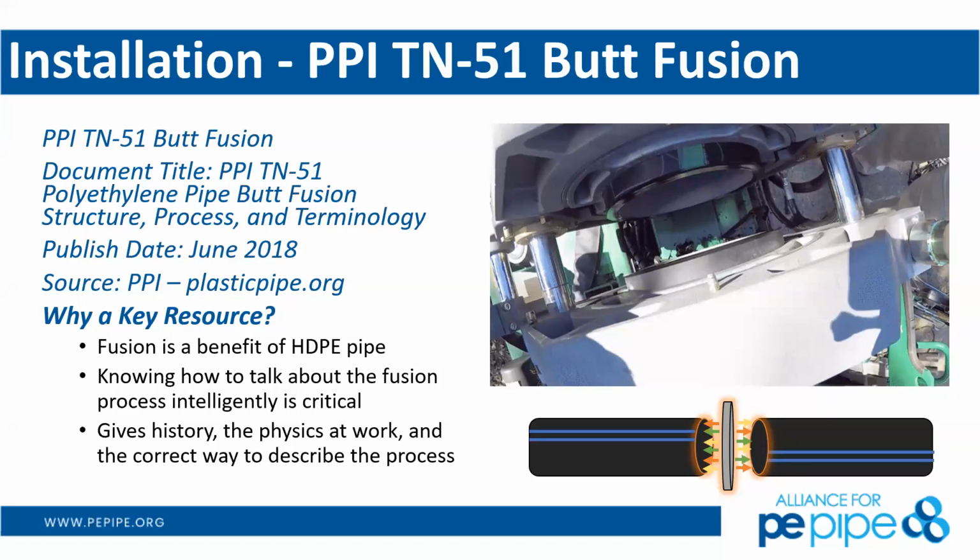And really, polyethylene has some incredible characteristics and properties, but I think the heat fusion joint is probably one of the most critical for water and wastewater applications. It basically gives you a zero leak rate. You have no other materials in there. You don't have rubber gaskets that are going to fail 10, 20 years down the road. And it's one of the reasons why we can provide a 100-year service on a properly installed, properly specified polyethylene piping system.